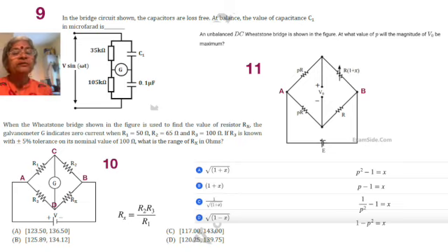We see that Rx is equal to R2, R3 divided by R1, of which 13 by 10 is already ready, multiplied by 105. Okay, so because it's easier, because 13 into 105 gives you 1365 divided by 10, 136.5. That's answer A. And the other part of the answer is easily obtained as 13 by 10 into 95.